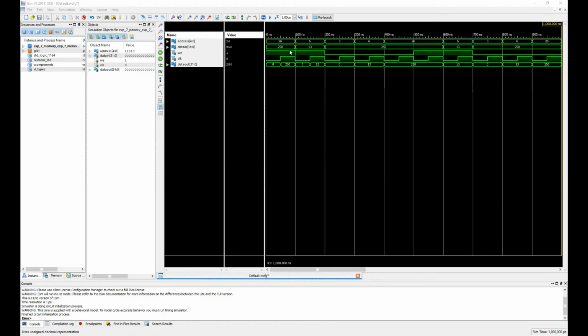in the address. So in the specific address, for example, for the first one, I have chosen 26, and the data is 250. It has the clock signal at the first point as 0, but we have the enable as 1. So it's going to store the value of 250 in this address. And I have the data output.